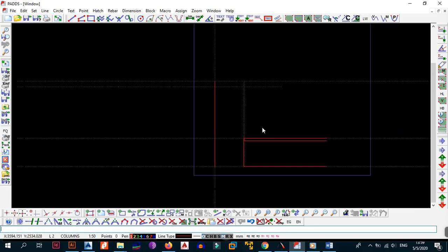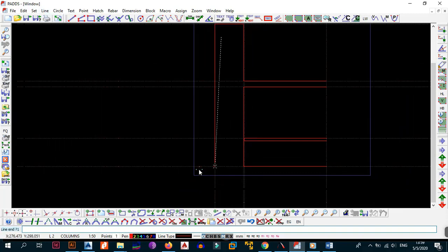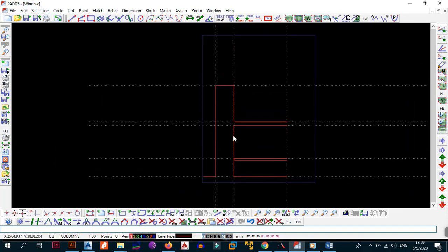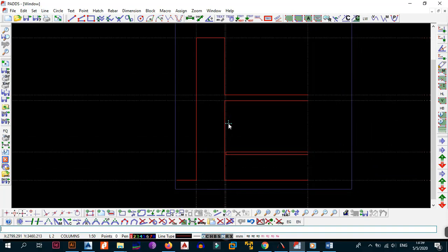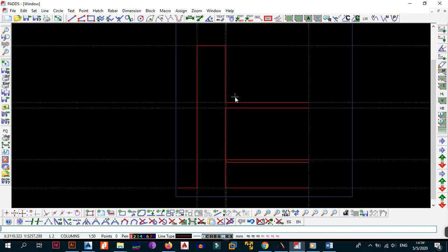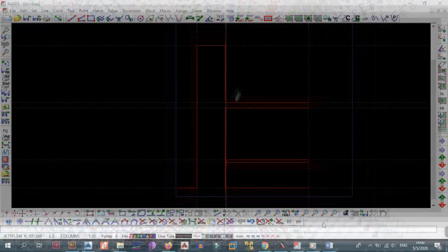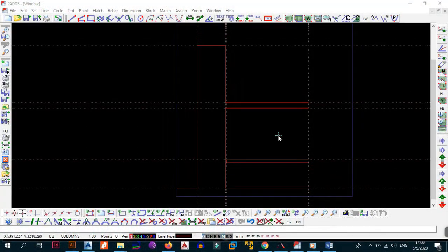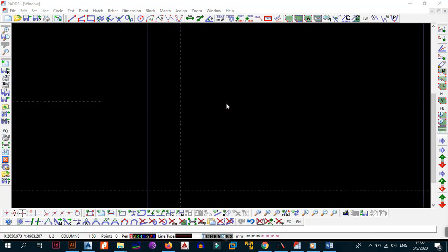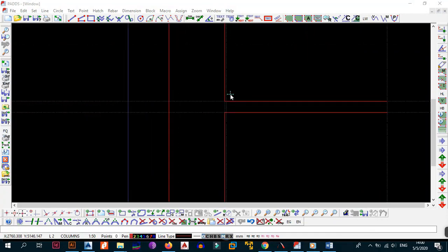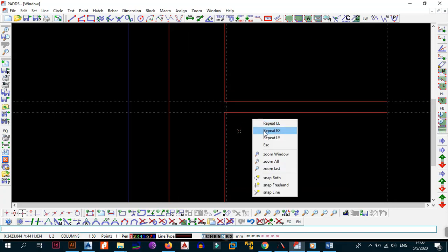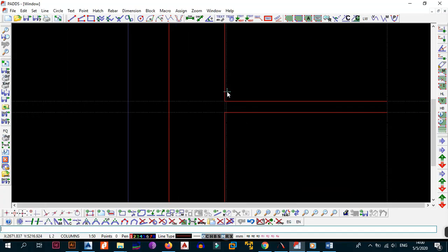All right, now that we have just established the main outside of our column, the main concrete structure, the next thing we need to do is to put the lines for the levels so that we see how we are doing it before we proceed. What I'm trying to say is let's add some visual guides to the line work. In this case, what I referred to by visual guides is let's add some dimensions and also some level markers.